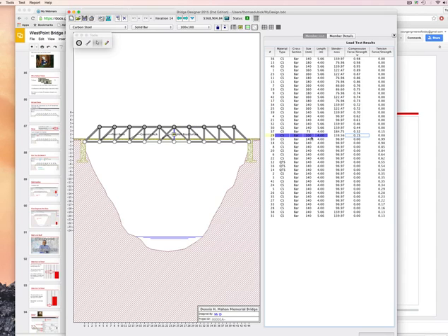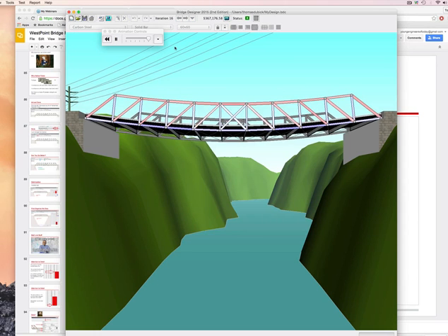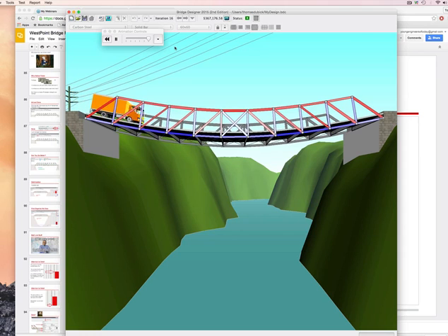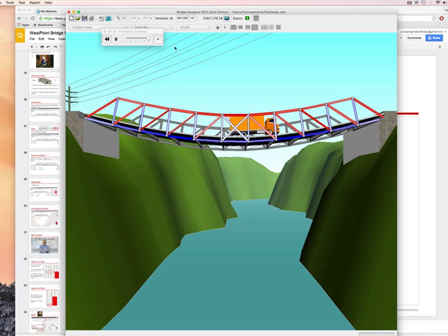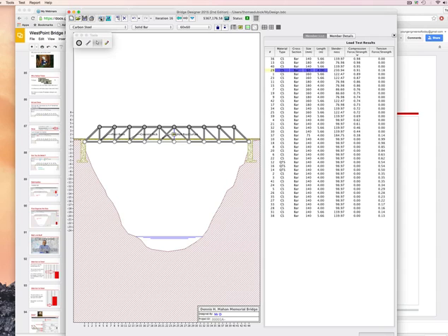So here's 0.15. That's probably way overkill. Look how strong, it's probably very strong. It doesn't have much of a load on it. So with that in mind, I can make this one smaller. And I can go over here, see where this is? I can click it and make it a little bit smaller. Run a test. Let's see if it still works. We're in luck, it works. And I got my price down some more.